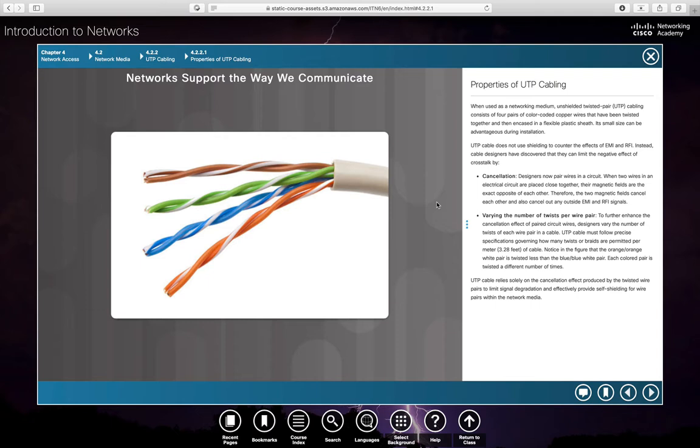There are different categories of wires that we will probably talk about, but Cat3 is telephone. The Cat stands for category. Cat5 was Ethernet for a long time, then it was Cat5e, and then Cat6 and Cat7. And as you move up, typically the speed that you can send increases, and at those higher frequencies you need more twist per foot to keep that cancellation effect working correctly.